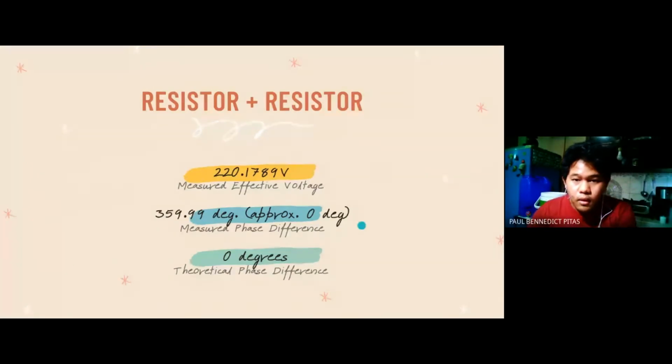In getting the phase angle difference measurement, for every circuit configuration, both a voltage probe and a current probe are placed in the circuit to display the sine waves of the total current and total voltage across the circuit. Using the waveforms of the total current and total voltage, the time difference, which is delta x, is measured and recorded.